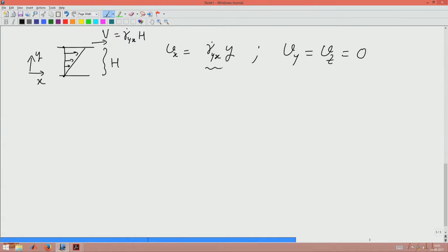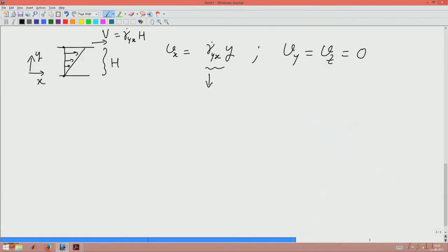A note on this usage, in general we are only describing a one dimensional situation right now, because this flow is one dimensional, but we know that there are 9 components of strain rate tensor and 9 components of stress. So, to remind ourselves of that, we will always use this gamma dot Yx. So, right now gamma dot Yx is the component. If you have to think in terms of overall strain rate, then del Vx by del x is 0 or non-zero? 0, right, because Vx is not a function of x.